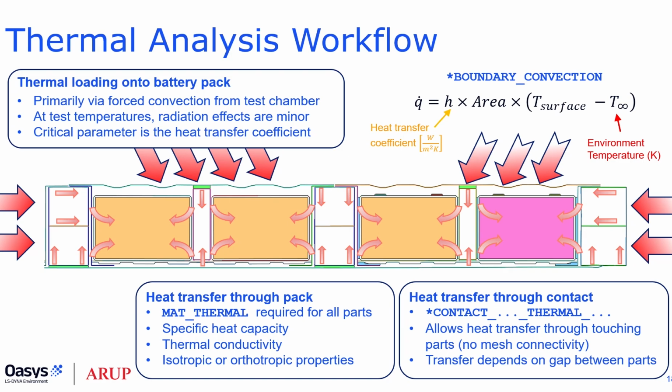For heat transfer inside the pack, for a thermal analysis, each part must refer to a *MAT_THERMAL definition that defines its thermal properties, i.e. specific heat capacity and thermal conductivity. If we wish to, these can be isotropic or orthotropic properties.